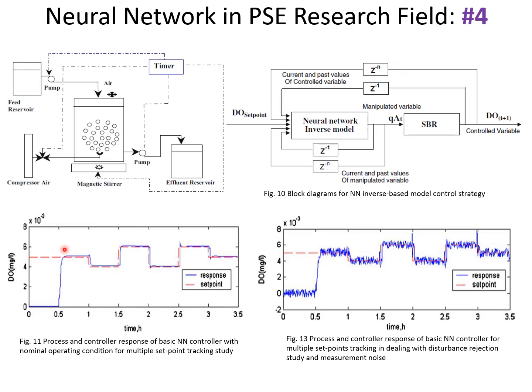We also have disturbance, which we don't show it here. And then here we have disturbance as well as measurement noise. Some disturbance comes in, it rejects it, and we also put noise into the system to make it look real. The real world will have noise coming from the actual measurements of the DO. So it's a real noise, but it still can control.